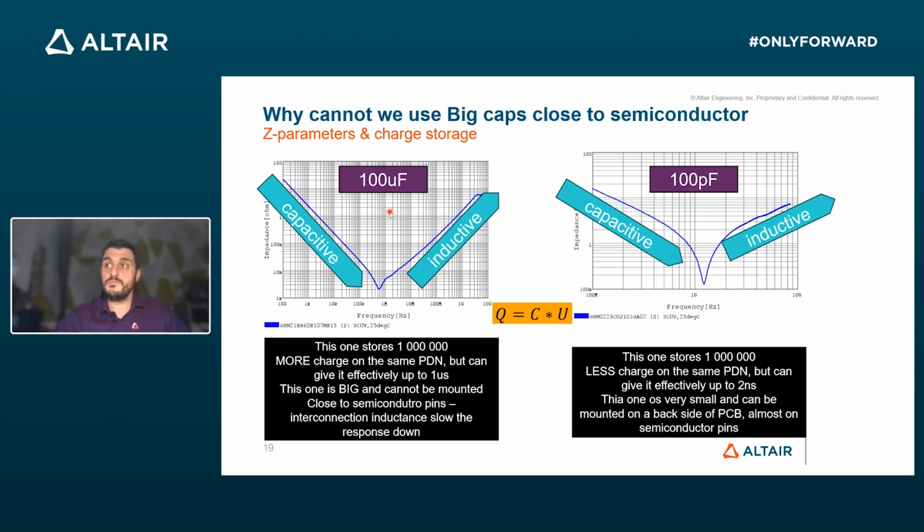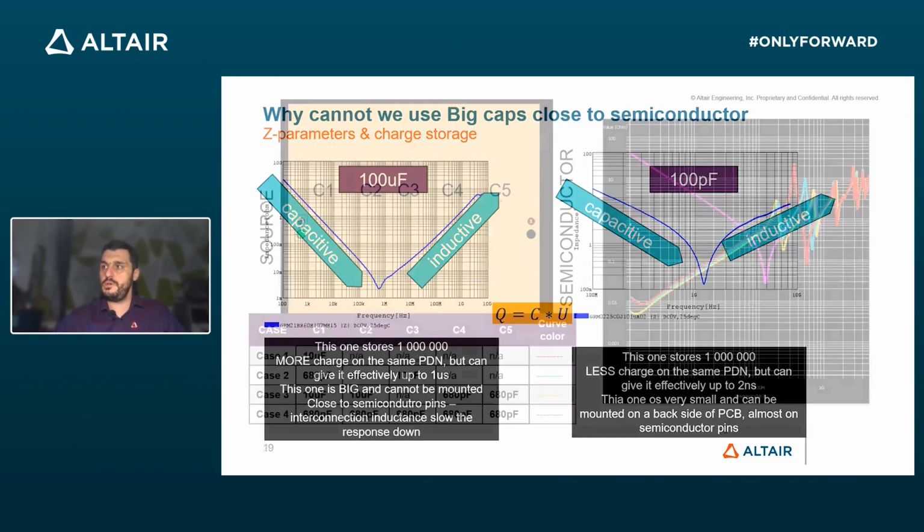Like this, the bigger capacitors can store much more energy. They are super tanks, but on the other hand, because of their size and their construction, they operate as a capacitor only up to a very low frequency. That's why you can see on the circuits multiple capacitors with multiple values connected between the connector and the sink, or the place where you need to draw the energy.